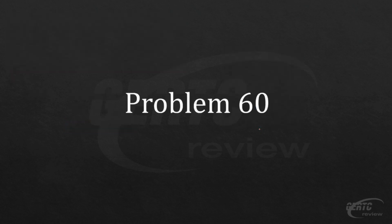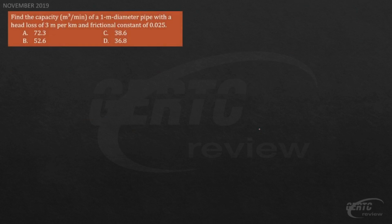Alright, next problem. 60. November 2019 pa rin. Find the capacity in cubic meters per minute of a 1 meter diameter pipe with a head loss of 3 meters per kilometer and frictional factor of 0.025. Friction factor yung ibig nga sabihin dyan. So, we will use the Darcy-Weisbach formula.